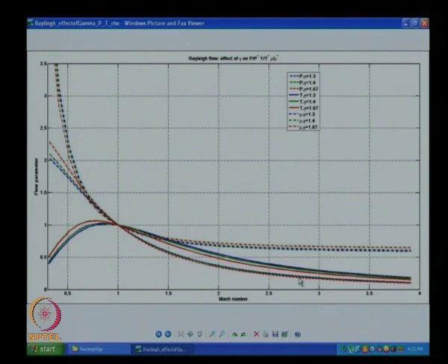Anyways, this one is your pressure curve, and if I start with some higher Mach number and I heat the gas, it is going to go towards m equal to 1 and the pressure increases because Mach number drops. Okay, that is an easy way to remember it. Now, I will look at temperature. That is going to do the same thing here, only in the subsonic side there will be a small change where I will now use density as my explanation. Okay. I am going to say now I will look at density, then I will come back to temperature. I will say this dash dot line, for low Mach numbers the change in density is high when I heat the gas. Okay.